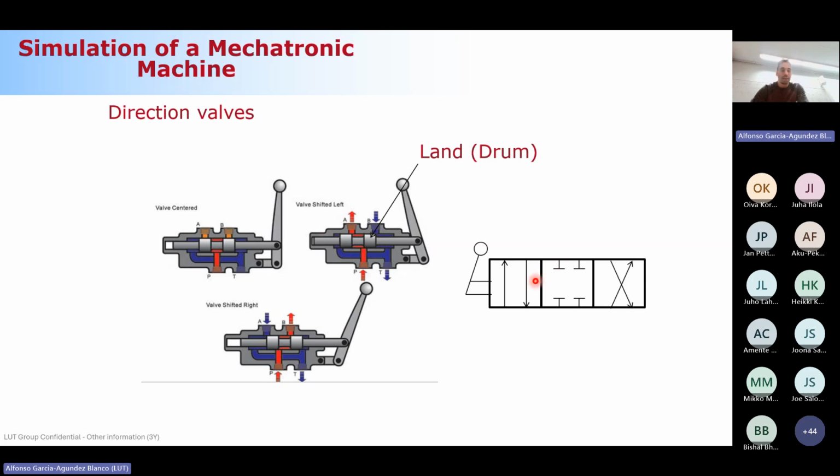So this port. In the tutorials, we were considering that this configuration was achieved moving the spool to the right, but here it is achieved to the left, okay? Clear? It's the only difference. It's just a sign convention, okay? But please always understand the representation with the physical motion, okay? It's the important thing. Clear?